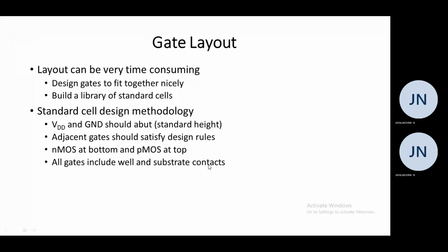So whenever you are constructing a layout, the construction of this layout is very time consuming. And whatever gates we are going to design have to fit properly. And also, we need to build a library of standard cells. So this standard cell design has some methodology and it has to follow certain rules. Usually, whenever you are constructing this VDD and ground, these two are power supplies, should be in standard height, and